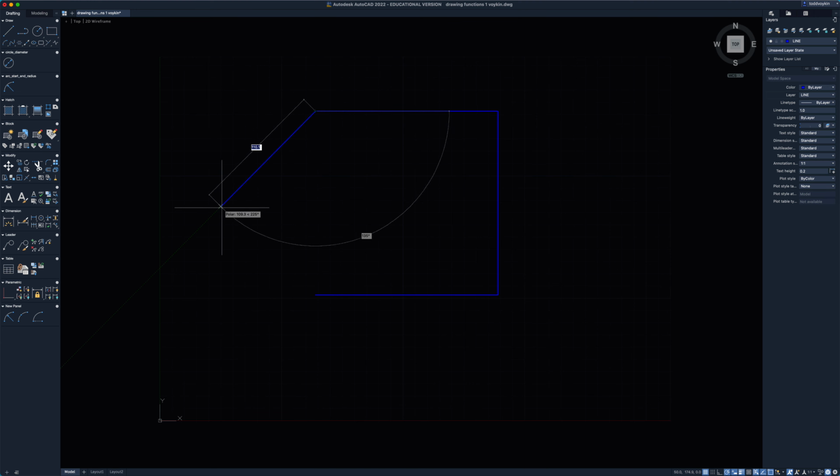And the last way to finish off this symbol would be, instead of typing close or typing in the dimension, I can just come down until it snaps to that end point, gives us that green little marker right there, and it says end point. Click, I'm still attached, right click out, and let's move on to see what it says next.